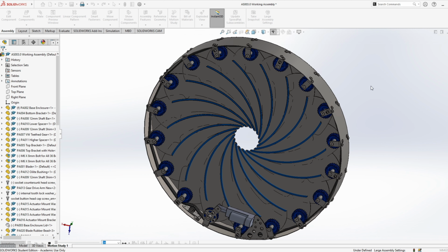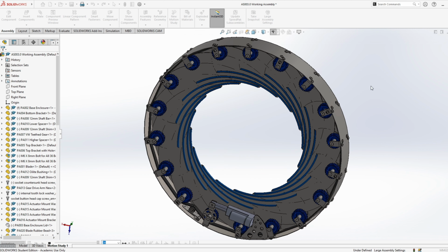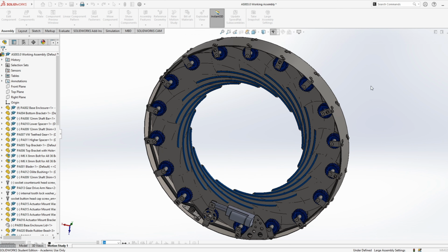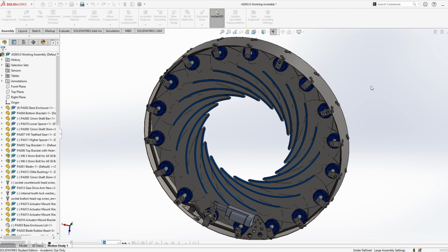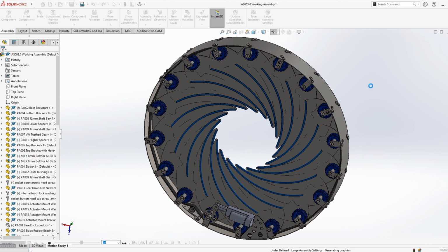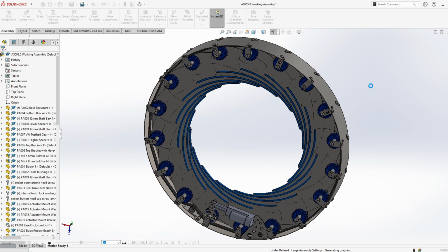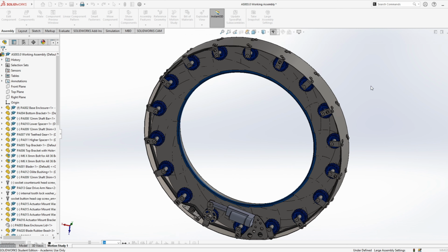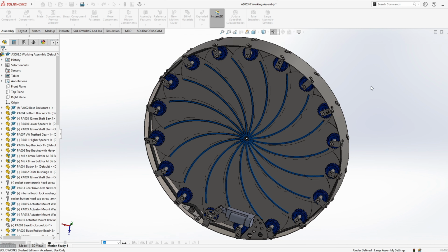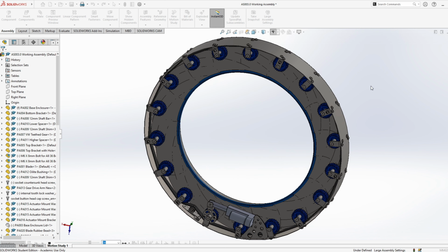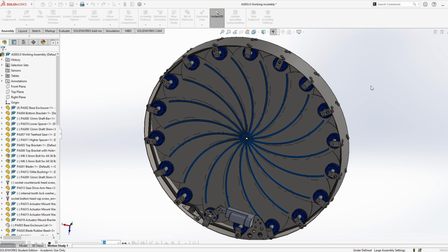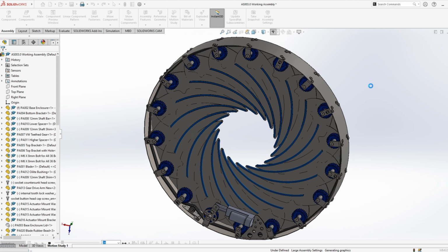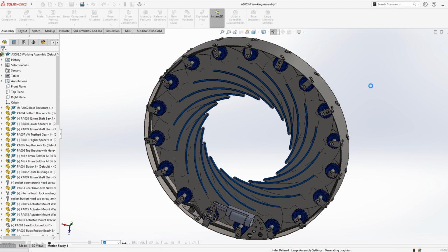Okay, so let's say I did design my aperture to the same spec as the illustration I just covered, or by having the same mechanical technique as your typical camera aperture. I would have required advanced machining, that being CNC milling or laser cutting, depending on the design of course. So that would have been moving away from fabrication and towards more expensive materials, machining. Also, a larger number of additional parts, equal sized adjoining linkages, plates would have been required.